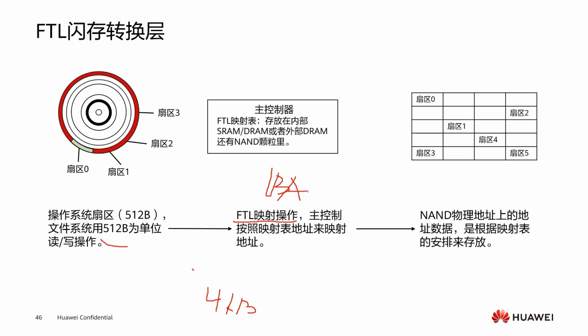Because FTL is the most important core technology in SSD design, no manufacturer is willing to disclose this technical information, and there has been no technical specification standard in the industry. The importance of FTL lies in determining the service life, performance and reliability of an SSD. Once there is a problem with FTL, it will cause data read and write errors. What's more serious is that the SSD cannot be accessed. An excellent FTL can not only extend the life of flash storage, but also optimize read and write performance.